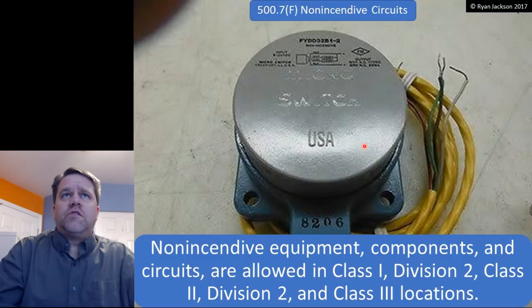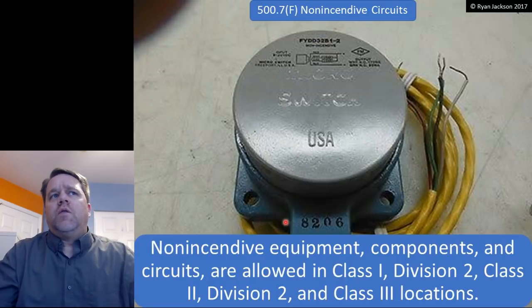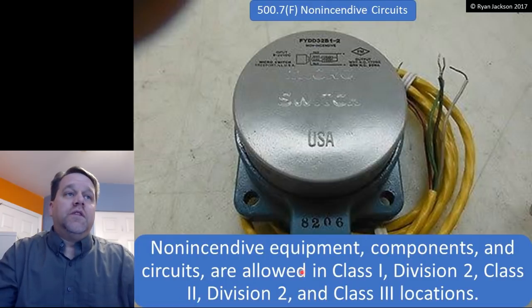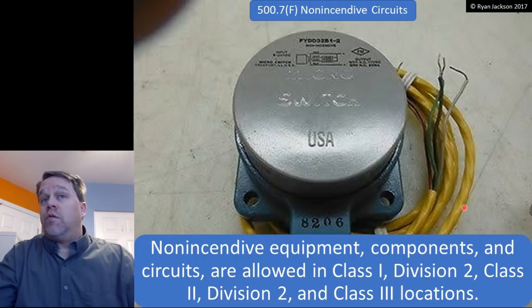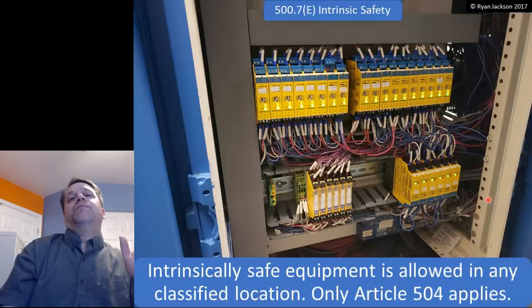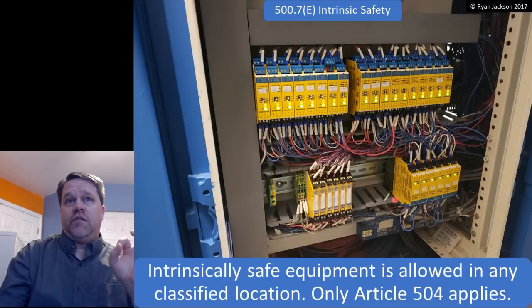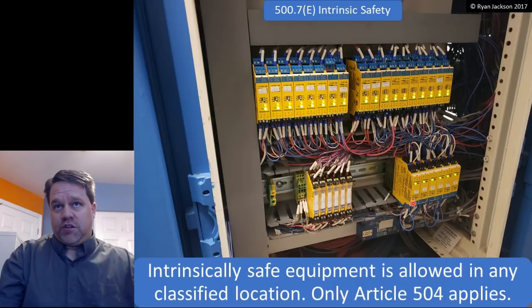Non-incendive circuits, non-incendive equipment is similar to intrinsic safety, but non-incendive equipment, components, and circuits are only allowed in Class 1 Division 2 or Class 2 Division 2 and Class 3 locations. Okay, an intrinsically safe system, you cannot create an ignition with it at all.